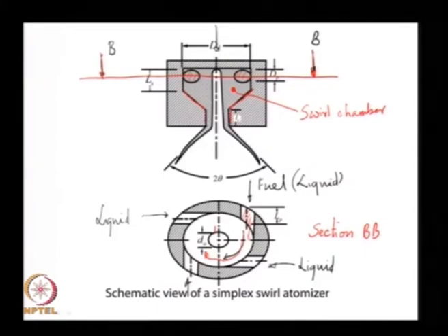So, this part is called the exit orifice. It is just a straight hole, except if I look at, if this whole orifice was filled with liquid and the liquid is swirling, essentially it is just like a spinning bucket. I create a void in the middle. Because of that, all of this is essentially air. It is exactly like a spinning bucket.